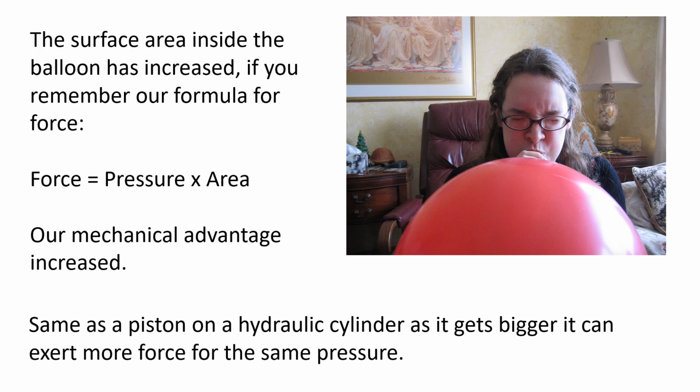As we blow up the balloon, the surface area inside the balloon increases, thus giving the pressure more surface area to act upon, thus increasing our mechanical advantage. That's why if we increase the size of a piston, but leave the pressure the same, we'll be able to exert more force for the same amount of pressure.